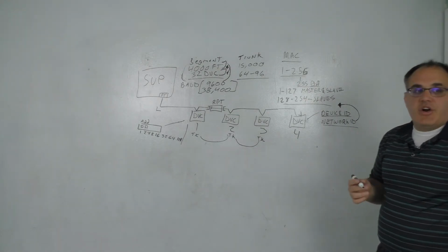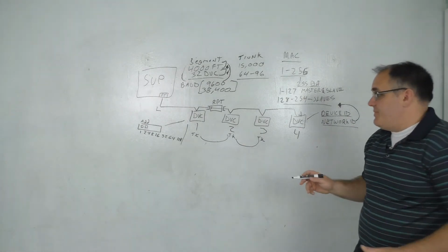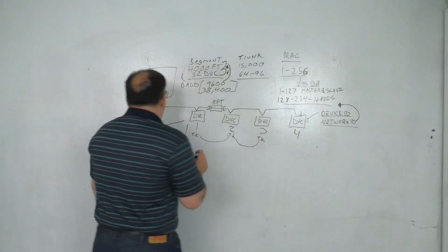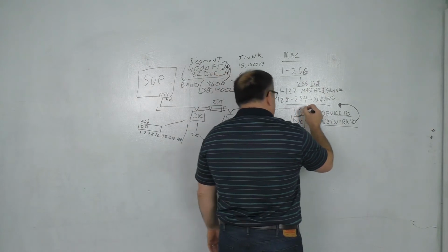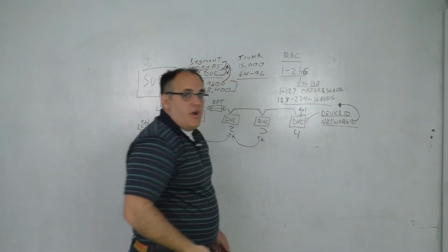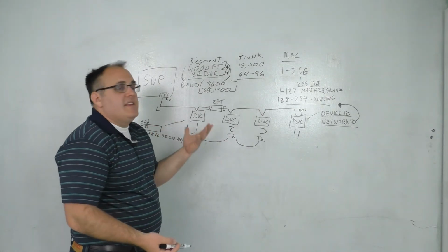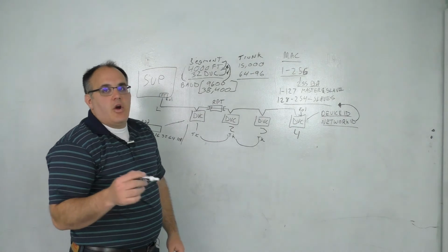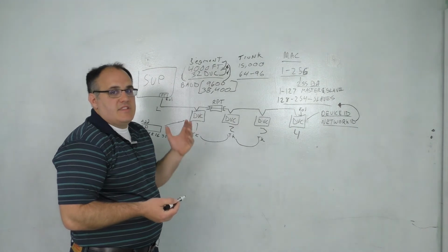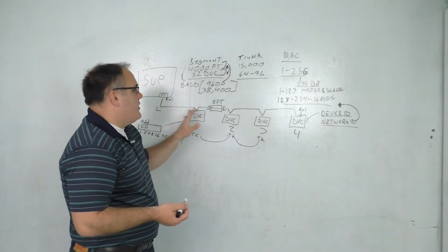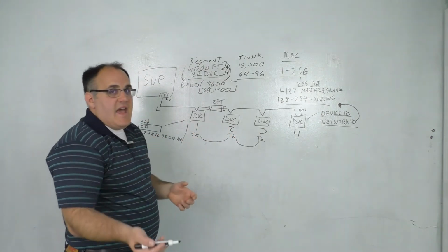All right, now we're going to talk about the next physical part of BACnet MSTP, which is end of line. You want to set your end of lines so that your trunk knows where it ends. End of line is essentially terminating the trunk with a 120 ohm resistor. And that is telling the trunk, hey, this is where the line ends, so it doesn't keep communicating. So that is why we put end of line resistors on our trunks at the end of each run.